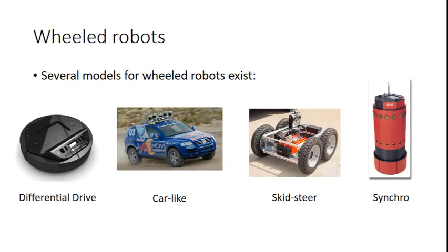And even within wheeled robots, there are quite a few different types. Here are just 4 common types. On the far left, we have differential drive robots, which is what the Turtlebot 3 is. It has 2 wheels moving independently of one another. And shown here, I have the base of the Turtlebot 2, which also is a differential drive robot. Carlike robots are, of course, wheeled robots.